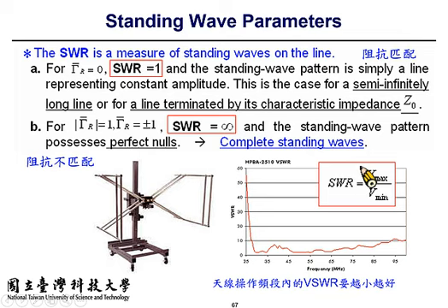On the other hand, starting from 30 megahertz and going all the way above 85 or 90 something, the SWR ratio is smaller than 10, which means that some of the incident power can radiate from the antenna. So this result satisfies the usable band of the antenna.